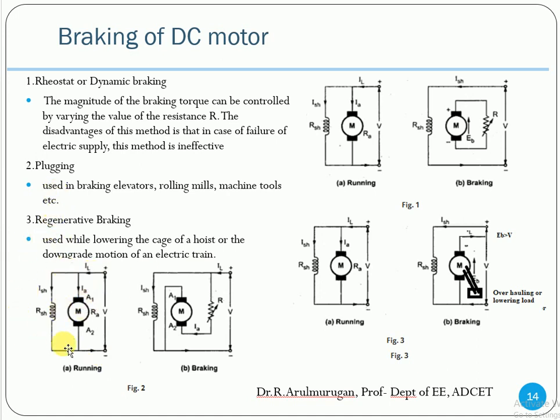under normal running conditions, okay, when you want to apply the brake by the plugging method, the A1 and A2 direction is changed. See here, plus is going to A1; instead, plus goes to A2, and then through that one.